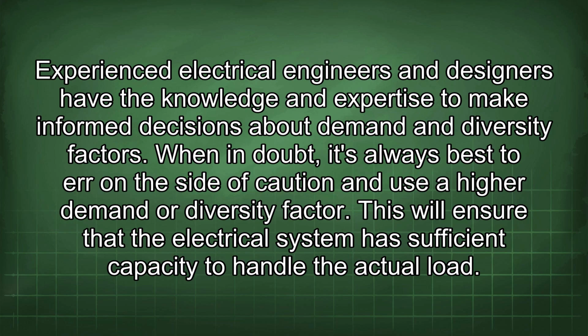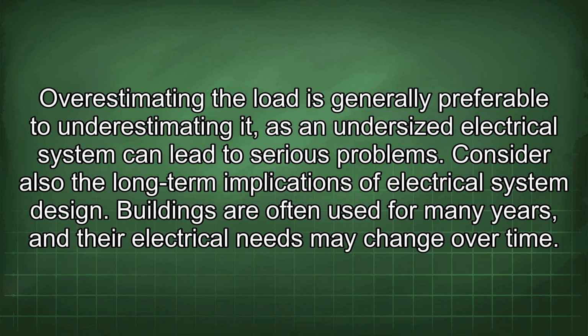When in doubt, it's always best to err on the side of caution and use a higher demand or diversity factor. This will ensure that the electrical system has sufficient capacity to handle the actual load. Overestimating the load is generally preferable to underestimating it, as an undersized electrical system can lead to serious problems.